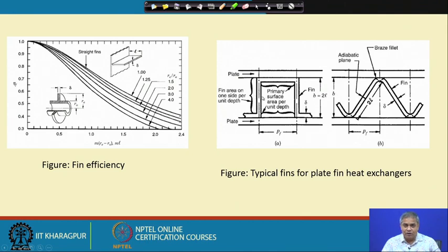It is very important to appreciate that most of the fins we have seen are attached to the base and go out of the primary surface, and the tip is not connected to any solid surface. But here it is a surface which is connected between two other surfaces which are at 90 degrees to the fin. Then there is no free end.